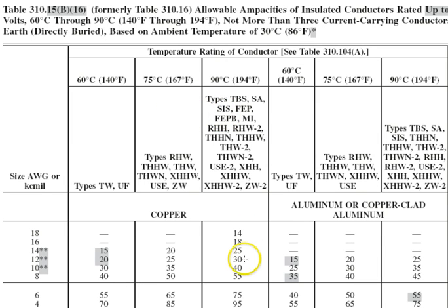In that case, you could use this column. But for residential systems, all of it on the DC side is 75-degree rated, so we're going to use this column for our ampacity requirement. We see that the first conductor ampacity we see is number 14. So a number 14 American wire gauge is rated 20 amps. So we select this conductor.